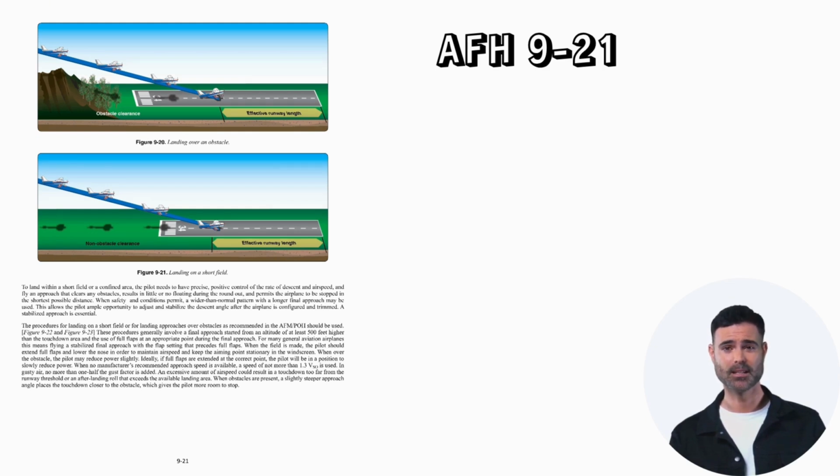When safety and conditions permit, a wider than normal pattern with a longer final approach may be used. This allows the pilot ample opportunity to adjust and stabilize the descent angle after the airplane is configured and trimmed. A stabilized approach is essential.